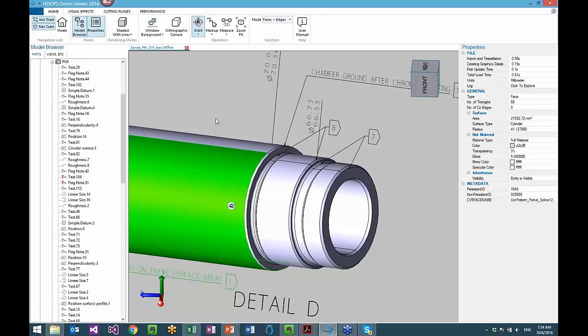You're not required to bring data in from a CAD file. You can author it yourself using HOOPS Publish, but this is a very seamless move from CAD data to PRC to PDF, because that PRC data is the core of how 3D data is represented within a PDF. So there's two ways. You can have this exact representation called PRC. There is another way called U3D that's just surface data, so your tessellated data within a PDF. Both are 3D data. Both can be embedded in a PDF. Both are supported by HOOPS Publish.